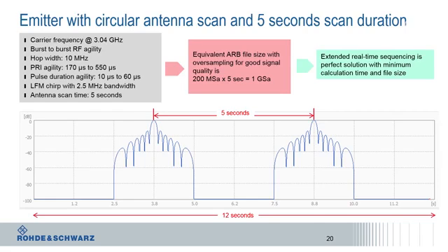Here you can see the envelope of the expected signal. I'm using a sin x over x antenna, which is doing a circular antenna rotation. From peak to peak, you can see the 5 seconds. I've recorded some more seconds in order to see how the total signal looks. Whenever there are no side lobes of the antenna, there's also no signal. I've assumed an antenna which does not have any back lobes.